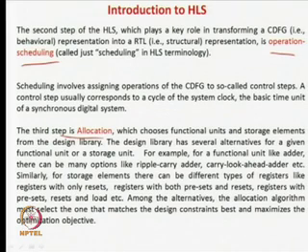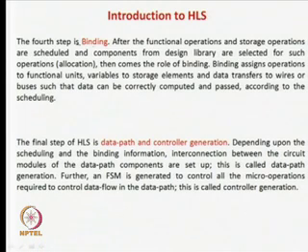The third step is called allocation. What do you mean by allocation? Now, we have an adder, and we say this is the adder, but how do you want to implement it? You can use a ripple carry adder, a carry look ahead adder, or a carry save adder. So, in the allocation step, for each of the operators like adder, multiplier, subtractor, we allocate a hardware block. We can also say that in this step we physically look at the design library, see what adders, multipliers, dividers, subtractors are available there, and try to allocate them to each of the operation nodes in the CDFG, or better to say, in the scheduled CDFG.